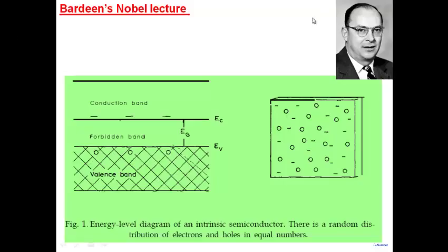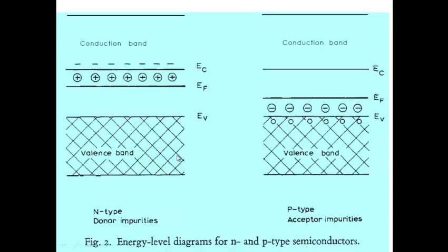You can see how liberally the energy band diagrams are used to convey what semiconductors are, how transistors behave, or how a p-n junction behaves. So you can see here a band diagram with EC, the conduction band here, the valence band here, and EG here. A diagram like that shows electrons here and holes here. The hatched region shows that it's completely full, except for a few vacant spaces here. You can see EF closer to EC, so N-type semiconductor, EF closer to EV, P-type semiconductor.